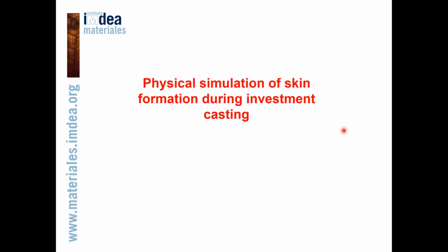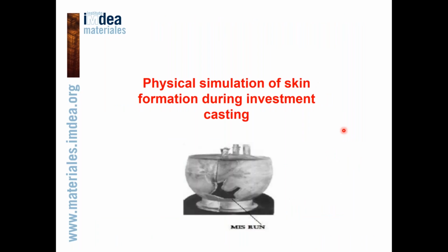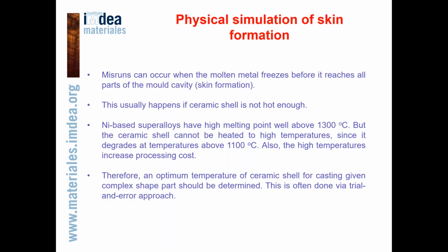So the next part of my presentation focuses on physical simulation of skin formation during investment casting. As I have already mentioned, misruns can occur during the investment casting process when the molten metal freezes before it fills the interior of the ceramic shell.